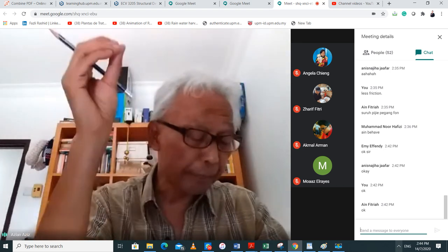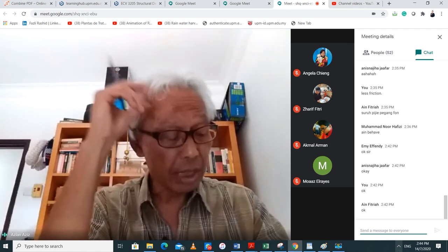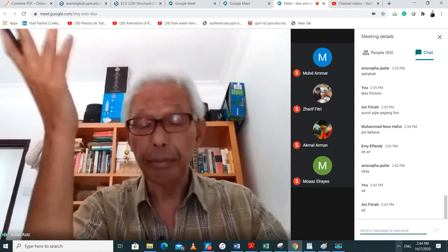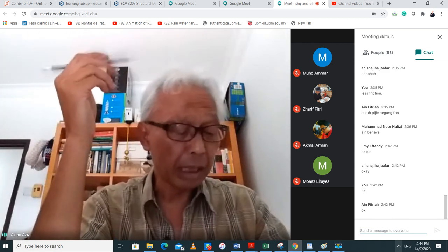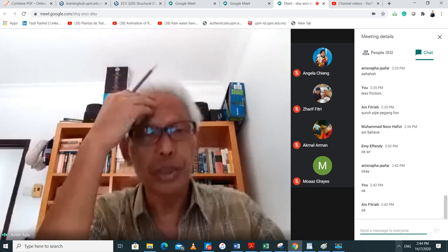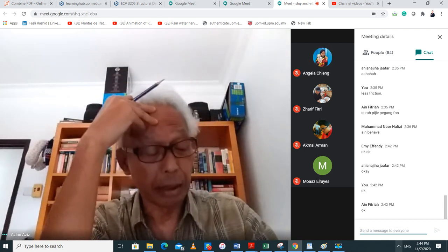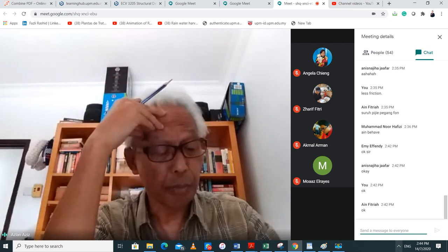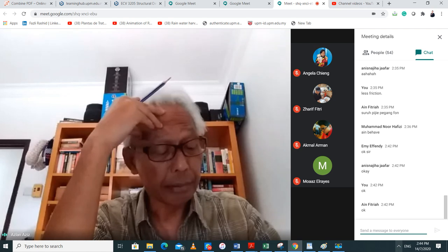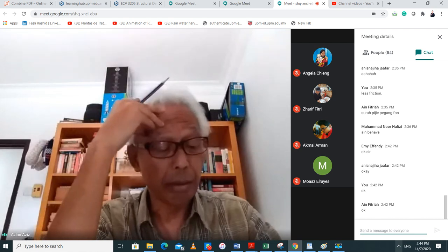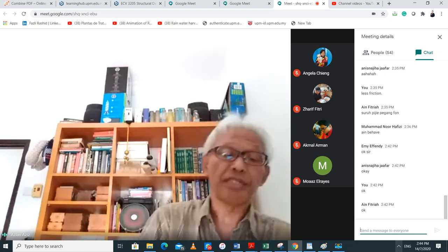So Y sub P, the depth, is just Y sub C, which we have calculated to be 0.3 by eye or by inspection, and then multiplied by N. N is a ratio of the pile diameter with respect to the cone diameter. So the pile diameter was 0.6 meter, 600 millimeter, and the diameter of the cone is 36 millimeter.